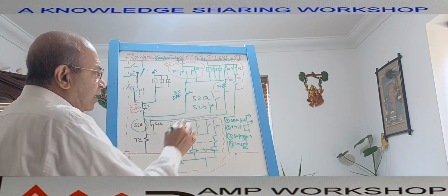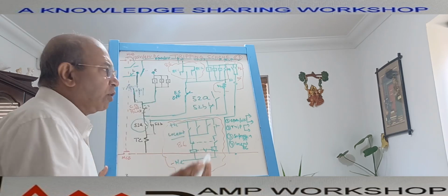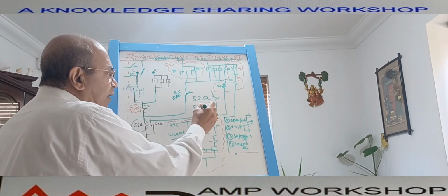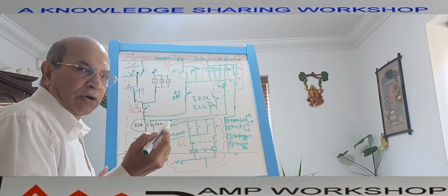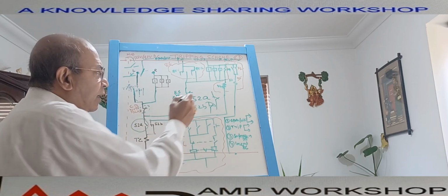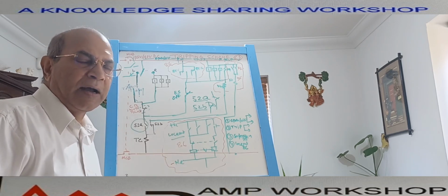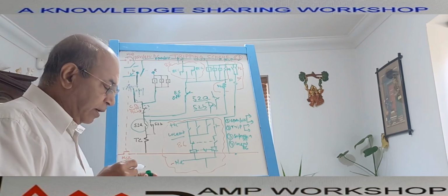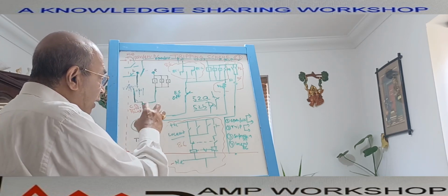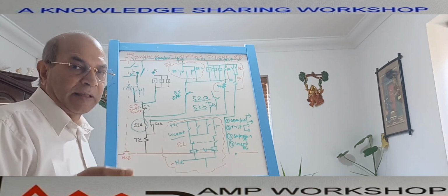that we call the normally closed NC contact. So the moment the breaker goes from the open condition to the closed condition, this becomes NC and this becomes NO, and on the reverse side, when the breaker goes again from the closed condition back to the open condition, then it becomes NO, it becomes NC. The contact is always shown in the de-energized condition, here it is considered as the open condition of the circuit breaker. So whether the circuit breaker is open or closed, we also need to know before tripping the breaker.